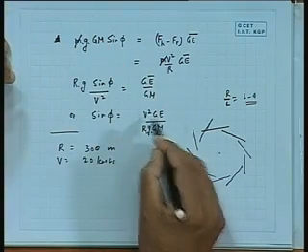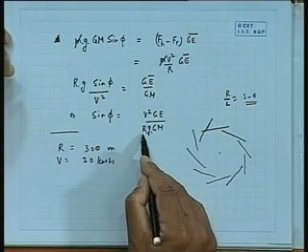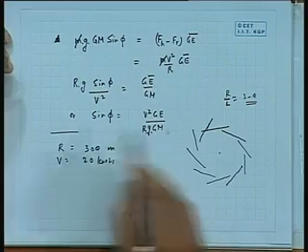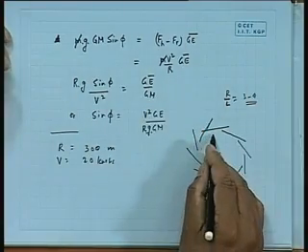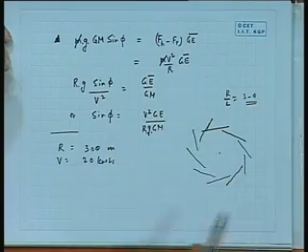If this increases, then there is an increase in the angle. If speed increases, there is an increase in the angle, or if R reduces, there is an increase in the angle. Therefore, the ship will heel more if it makes a tight turn, obviously, because the centrifugal force is more. GM, again you can make out, it is inversely proportional to GM. As GM is high, angle is low. If GM is high, obviously the stiffness is more, so you need more moment to heel.